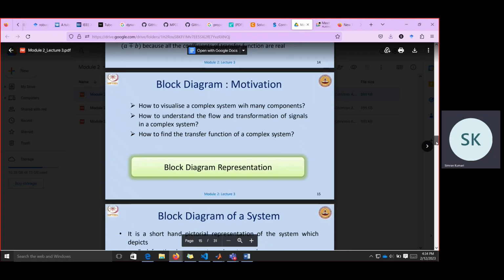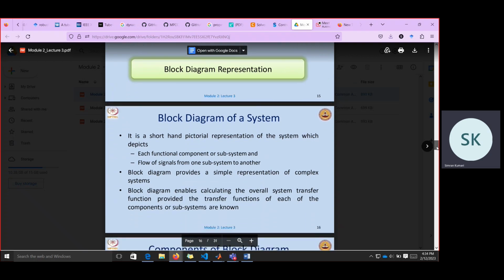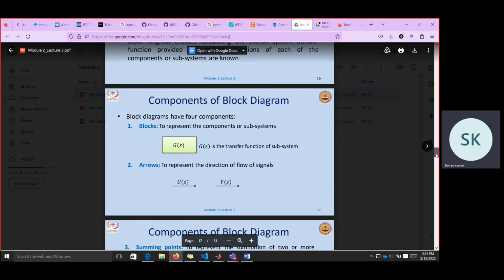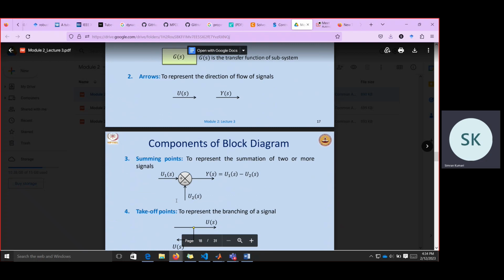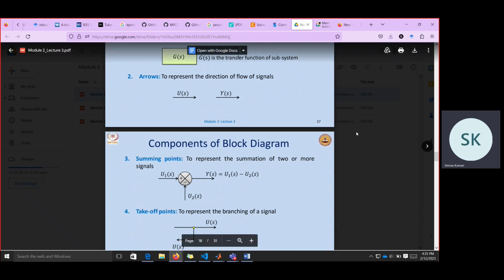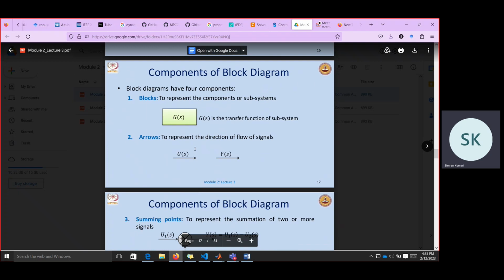Okay, then we went to block diagram representation, because any system we can say simply is a block in which input is given and output is obtained. So from there, there are different blocks. This is one of the blocks, which is the summing block. The lines, these arrows basically, represent the signals, and this one is a system. So this is a static system, which is a summing point you can say. And the dynamic system that we have, we represent by this rectangular block G(s).